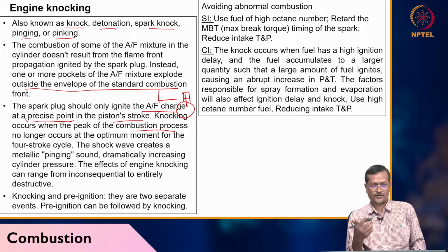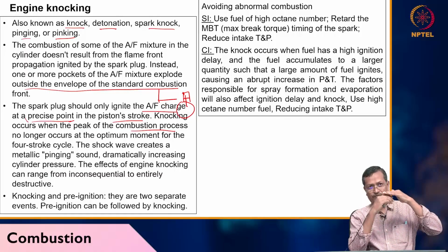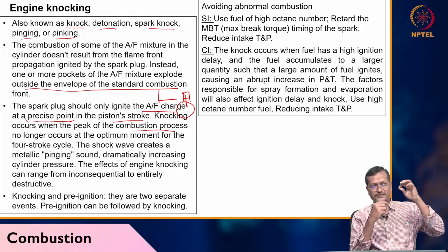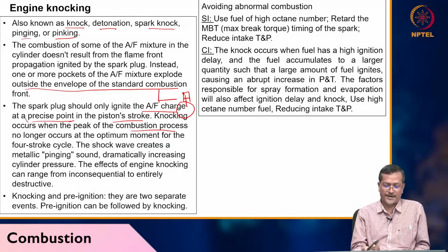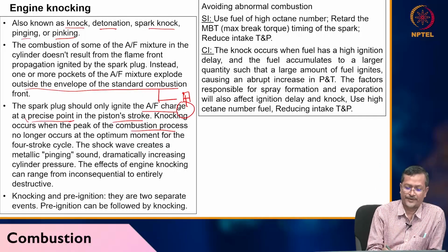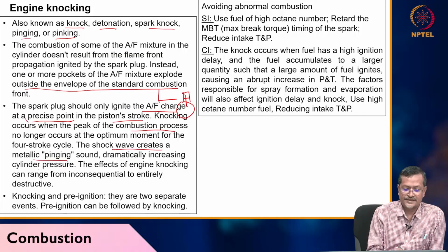In the four-stroke cycle, what you are doing is compressing air only. Fuel is not there. Fuel will be injected, and then because of the air temperature it will be burnt. Now, before reaching peak temperature, if it is burning, then again it is a problem. The shock wave created will produce a metallic pinging sound, dramatically increasing the cylinder pressure.